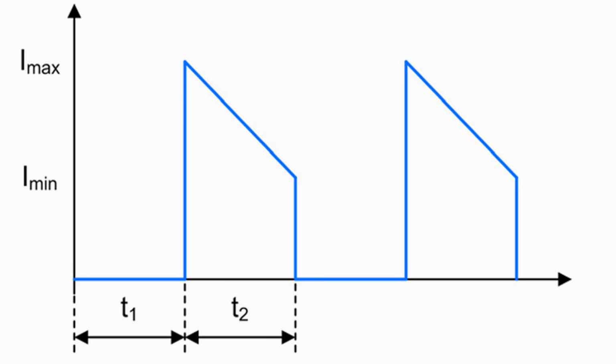And as a result, what happens is you just have to generate higher peak currents in order to get your average current on the secondary side to be adequate per your power supply specifications. But I thought that was just an interesting observation to make, to really bridge the gap and understand that it's kind of just like inductors that we're dealing with still.